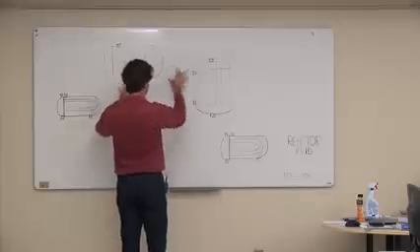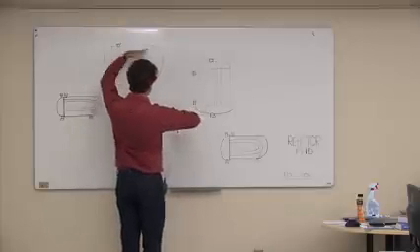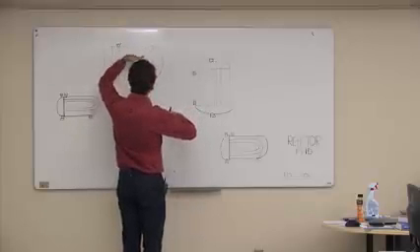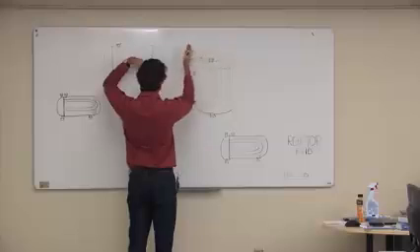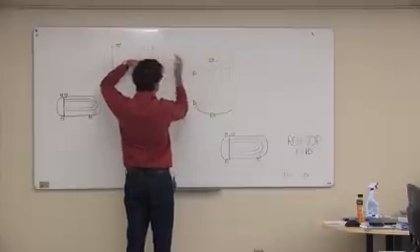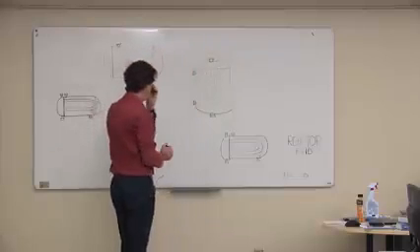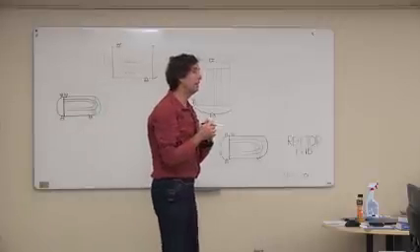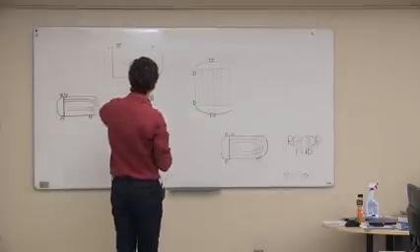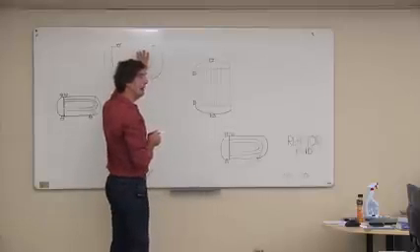We just need to have the elevations far enough that the liquid level in here is going to flow into the jacket of the heat exchanger. It's going to boil it and percolate it back up into the steam drum like that. So we don't need a pump for that. Do you think we need any other pumps though? What kind of pressure are we operating that steam drum at?